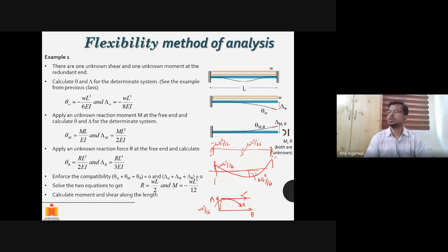So sometimes this approach is adopted, especially when you are dealing with very large forces. Then you are sure that the forces are going to be so large at the ends that my cross section is going to yield. I cannot avoid yielding here. So then still you can count on the residual positive moment capacity, and the beam will not fail. But if you don't have any residual positive moment capacity, let's say you design it in such a way that your hinges are going to yield here, but here your capacity is only WL square by 24, then your beam will simply collapse. Okay, if the hinges form and you exceed the moment capacity here also, then the beam will collapse.